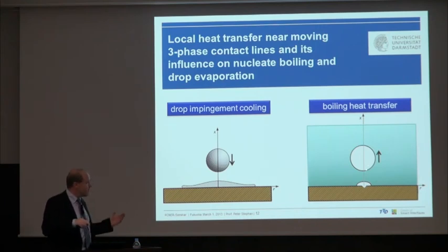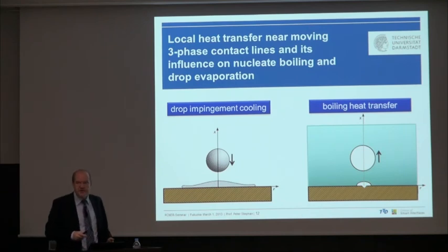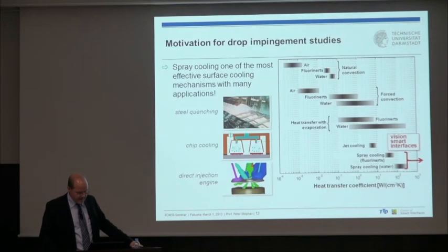And here just more or less the opposite. We have a heated wall and a subcooled or saturated, both is possible, liquid. So at a cavity, there's a nucleation of a single bubble or multiple bubbles, and this bubble is growing and finally detaching due to buoyancy forces and rising in the fluid.